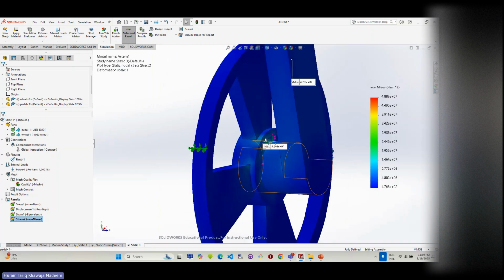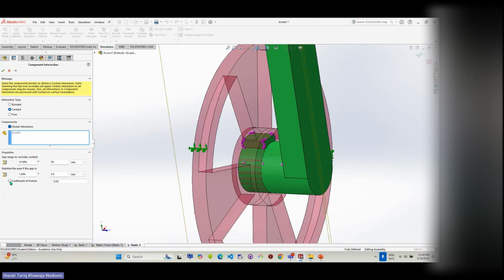Now, what is this? This is actually contact. So when you have contact, this means, look at this side. This side has no interaction, okay? And one more thing, which is the last thing, and then we finish. You can also, in the added definition, define the friction, okay? Maybe you have some friction on this side. So define some reasonable coefficient of friction between the aluminum and the steel and enter it over here. So you can define it.